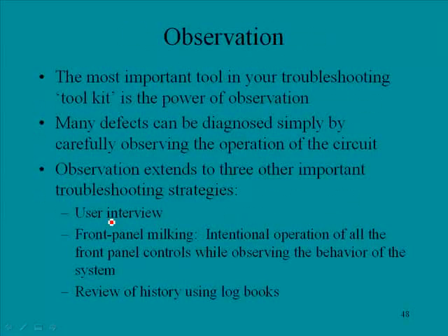Observation. The most important tool in your troubleshooting toolkit is the power of observation. When we say observation, this is all of the senses. You can see, but you can also smell, and you can also hear. Oftentimes in diagnosing electronic systems, it isn't just what you see. Sometimes it's what you smell that tells you a lot.